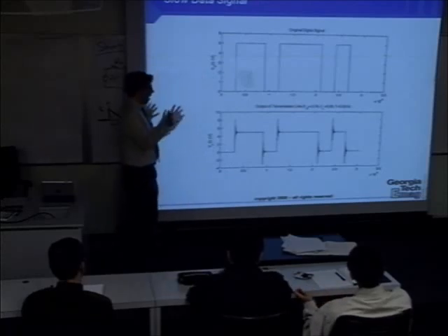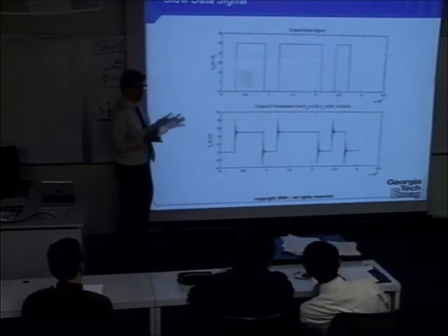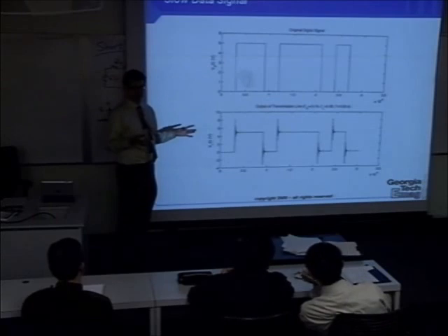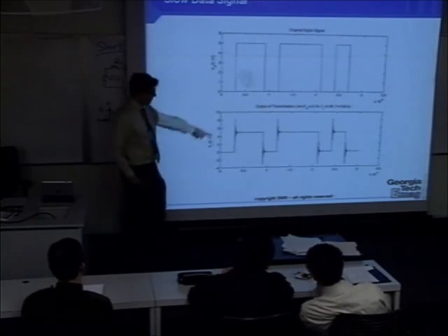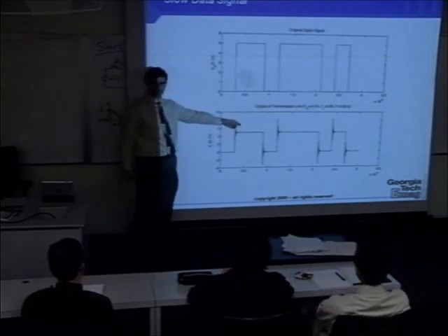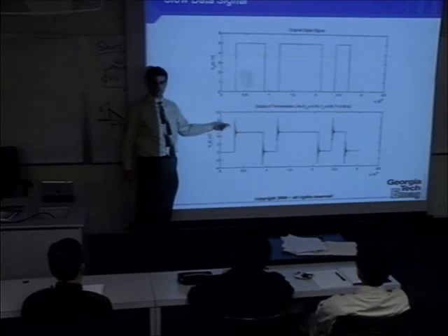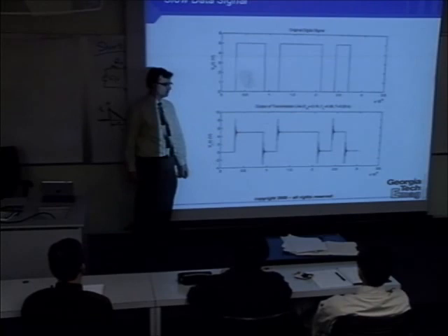Now, how would this affect this particular data stream? The answer is not that much. How would you get rid of this? There are a lot of different ways to get rid of this. You would want to use a filter. What kind of filter? No, opposite. Low pass filter.